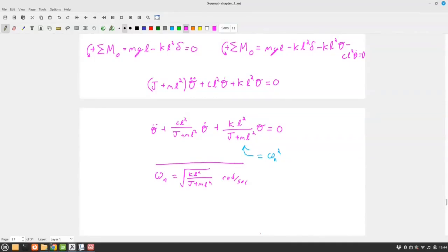And that gets you a nice, clean methodology for getting omega n. You can do the same for omega d, but for getting omega n out of a system, once you have it in standard form, what leads the displacement term is just a function of your natural frequency. How cool is that?